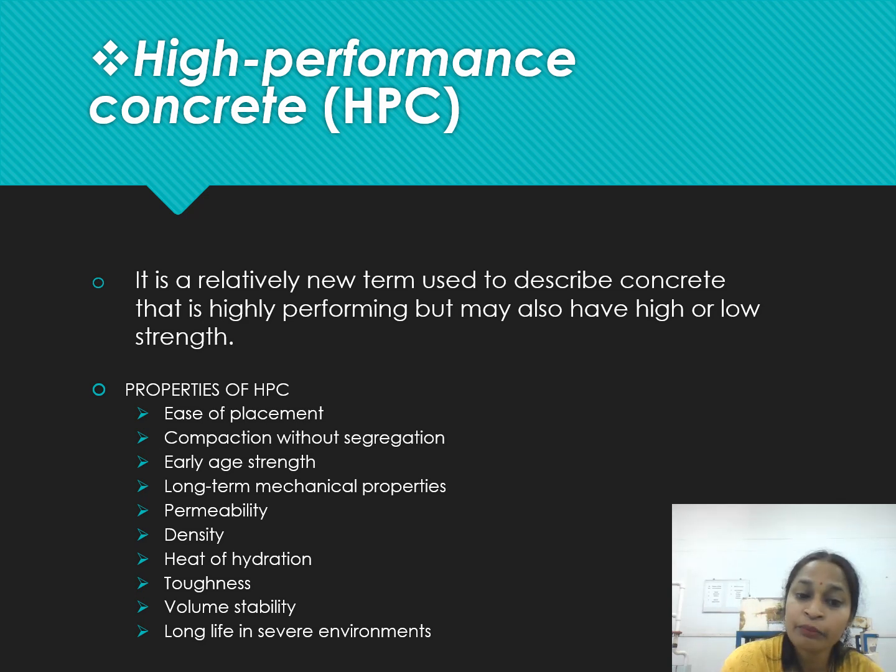Long term mechanical properties, that is your strength first of all, water absorption, etc. Like you have rains, and then again you have heat and cold cyclic loading on the structure when it is exposed to rain, summer and winter. So during this process you have these micro cracks, and when these micro cracks develop, after the next shower, what happens?